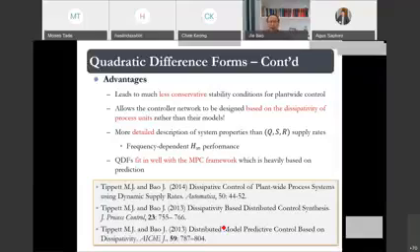Okay, and that means even the plant-wide performance description can be much more detailed. So we get a frequency-dependent H infinity performance, where we look at an H infinity norm with frequency-dependent weighting functions.